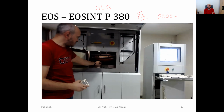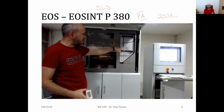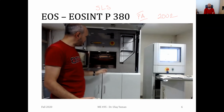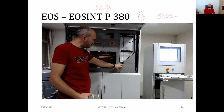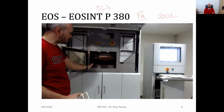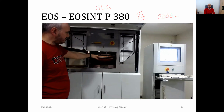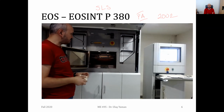And then we have such a carriage here. We have two powder tanks, right tank and left tank. You see now we have polyamide here up to this point. Once our carriage is on the right-hand side, some powder is poured into the carriage, and then the carriage moves simply from right to left. While moving from right to left, it spreads some powder on the bed, and then the laser performs some scanning and sinters the powders together.